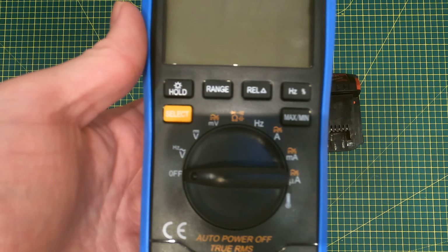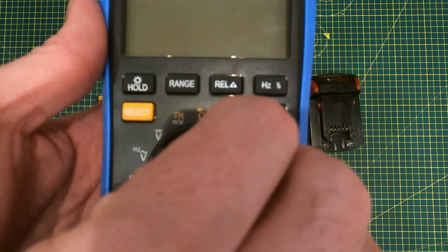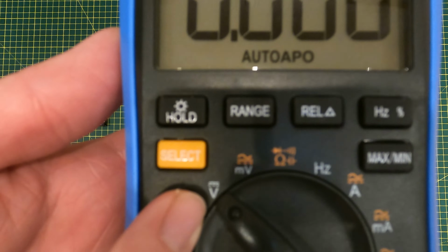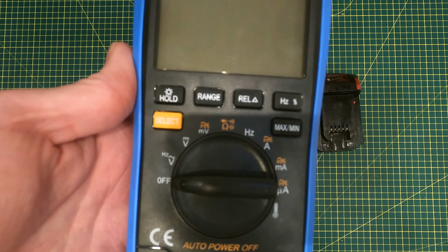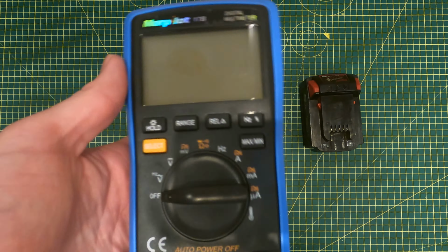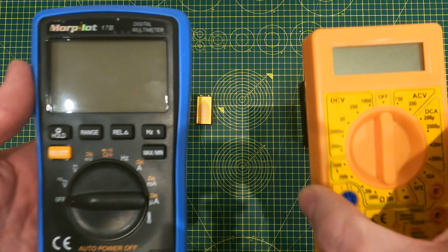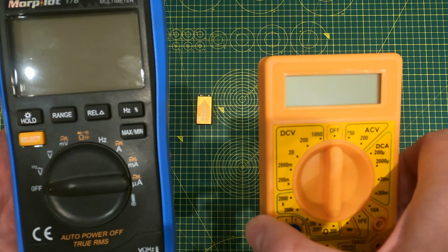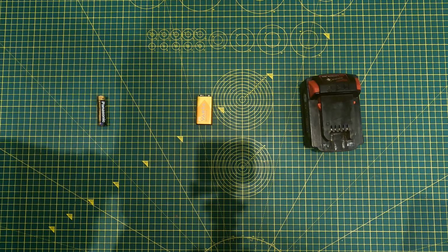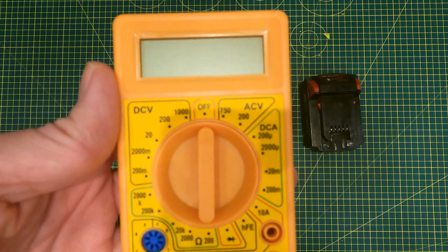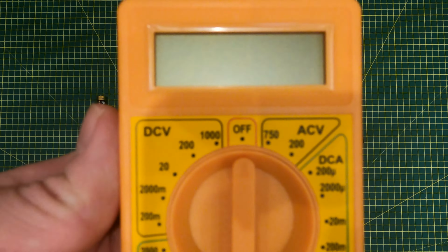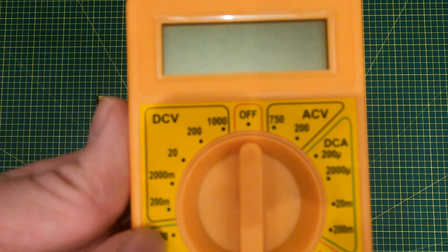Okay guys, so the first mode I'm going to be showing you today is the direct voltage mode, as displayed by the symbol there. What I'll do is I'll do it on the manual ranging multimeter. You have a choice. That's the auto range, that's the manual range. This one's slightly more involved, so I'll just show you how to do it on the manual ranging multimeter. So what you do is you'll take a look at the direct voltage symbol, again just there, and we have a selection of different values on the left.